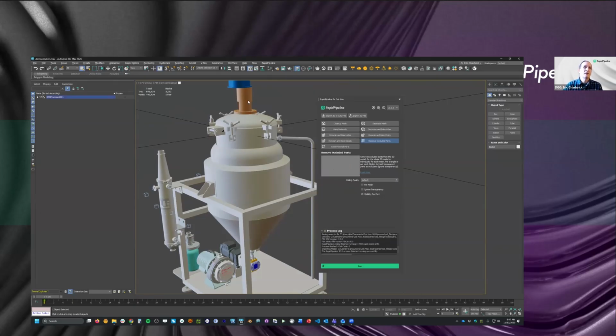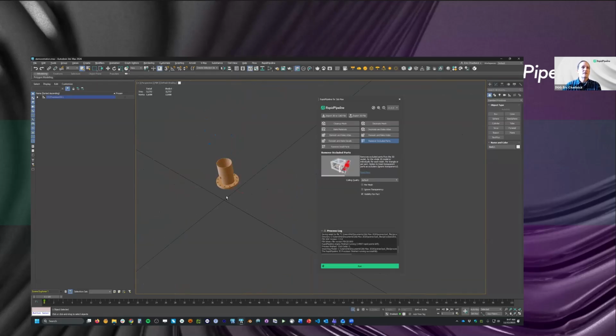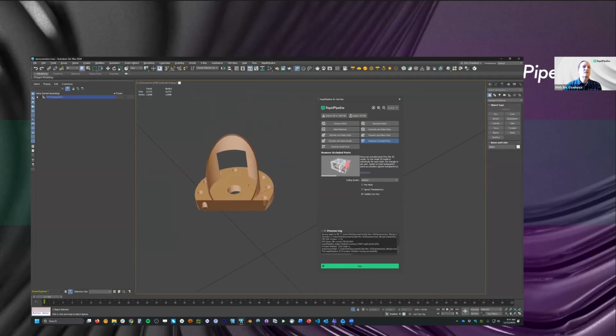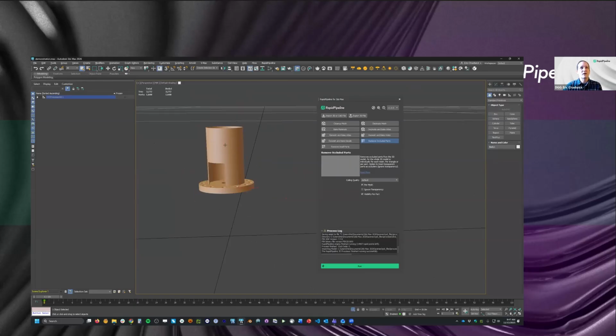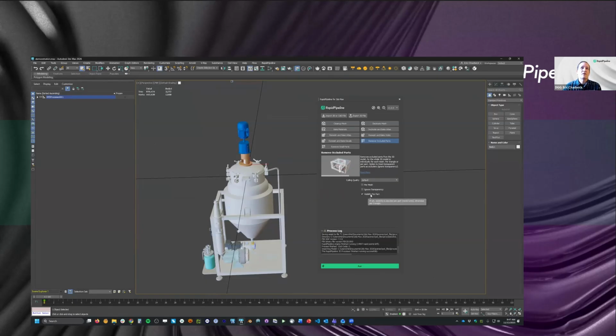So for example, if I choose a mesh here and I isolate it and hide everything else, this thing doesn't really work in this case because all the surfaces can be seen from the outside. But if there were internal structures inside of this thing, then per mesh would basically only look at those for each item and remove them from each item. Whereas with per mesh off, it looks at the whole mesh and decides, oh, parts of this occlude other parts and they should be taken out. So that's super helpful.